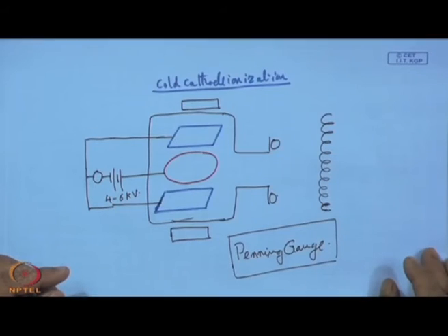So, in that case what we have is one auxiliary emitter of electrons, which is activated to release additional electrons, and once these electrons are in action, then this auxiliary emitter is switched off, and this is actually known as the trigger ionization gauge. So, that is the triggering of this emitter, which supplies additional electrons at the moment when it is needed, and this may be useful when we would like to switch on this gauge at a moment when the pressure is already very low.